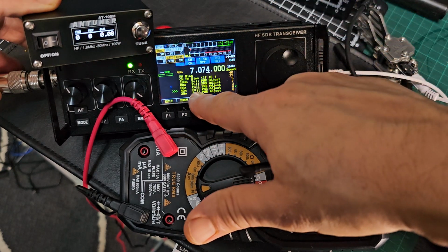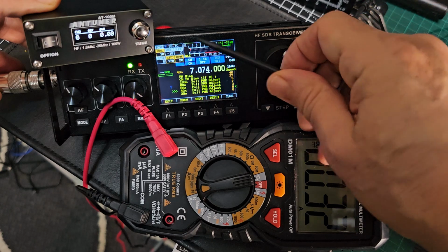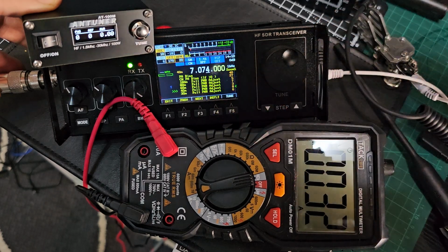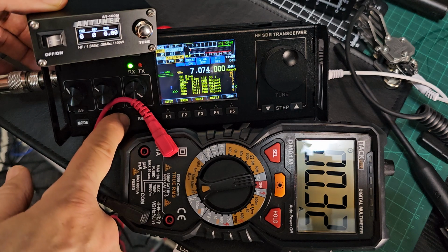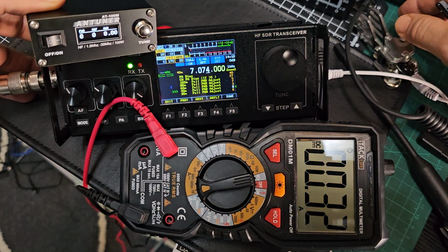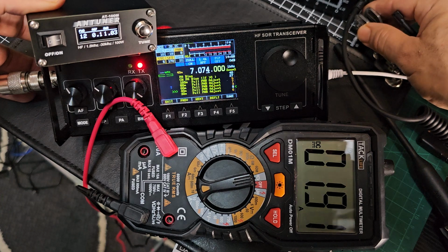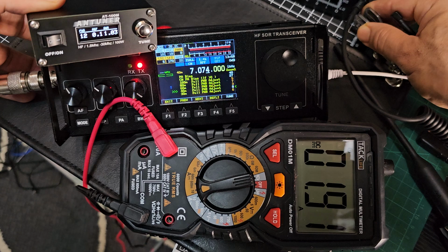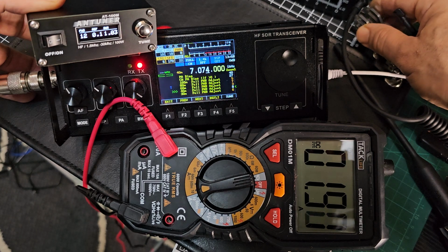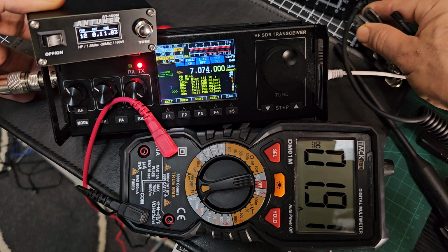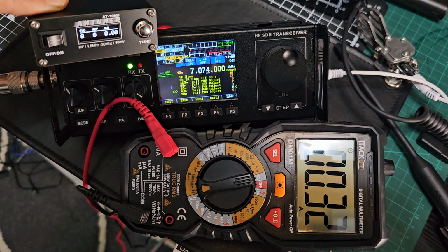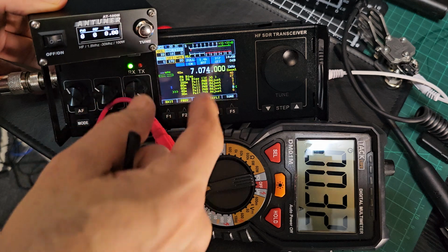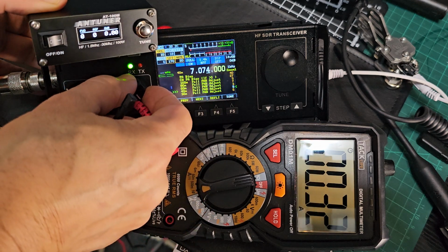And look, actually it's on full power adjust, so let's change that to full power. Going to press the PA, and there's a 5 watt one as well. Full power adjust, key up, and it's showing 12. I mean, how accurate are these things? 12 watts, yeah? And it should be 15, so, you know, we could up it. When we're actually transmitting, it allows you to up it, so it's at number 8 now. We're going to turn that to 9.